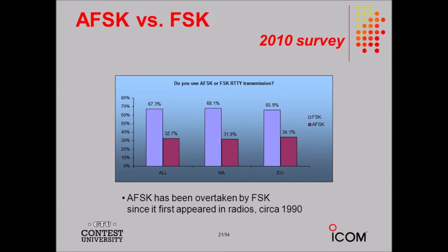Okay, top of page 437, frequency modulation. In frequency modulation, FM, the instantaneous signal amplitude remains constant. The instantaneous frequency varies instead. We can get FM by applying an audio signal to the varactor diode in a voltage-controlled oscillator, VCO. Figure 25.7 shows an example of this scheme, known as reactance modulation. This circuit employs a Colpitts oscillator, but we could use any other type of oscillator and get similar results.